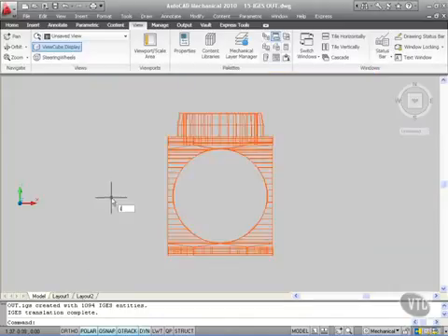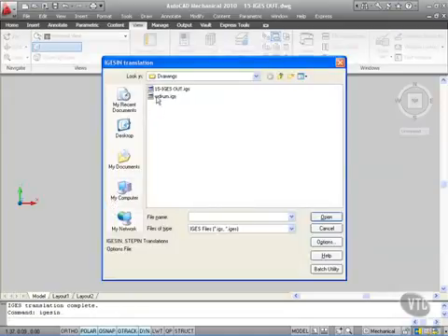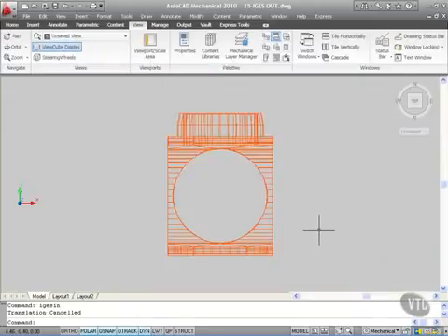If I actually type IGESIN and press enter, you'll see there that there's the 15 IGES out IGES file. So I'm just going to cancel that there. You see that it's an IGES file ready to be used. So that's how you export out as an IGES file as well as import in from an IGES file.